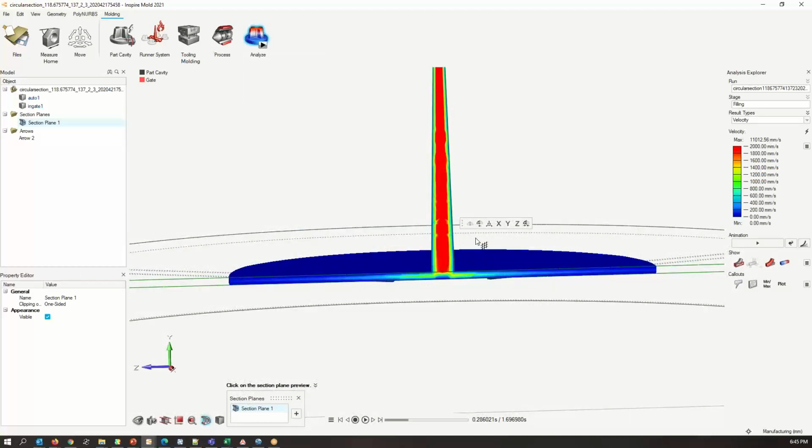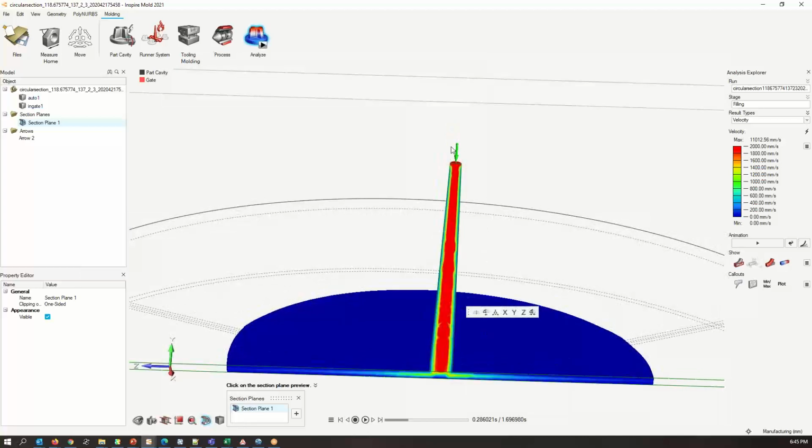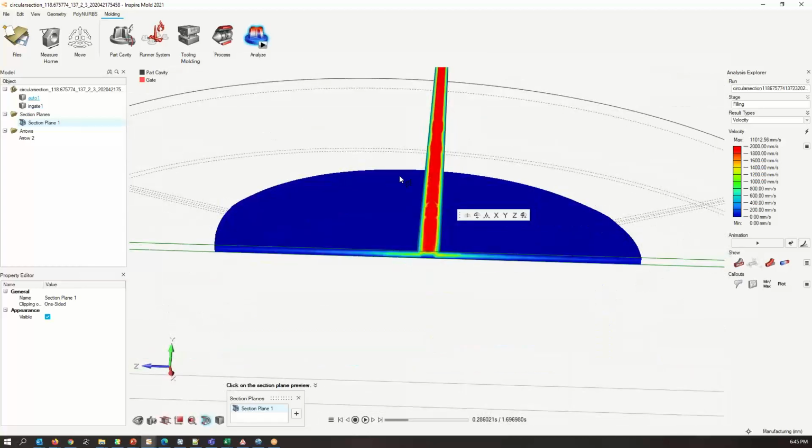And so as our flow front slows down, our viscosity is going to start going up out here. What happens back here is we're filling fast and we're going to be a little off center, and we're going to push out. But as this expands, our flow front slows down, and that's going to start building pressure back here.